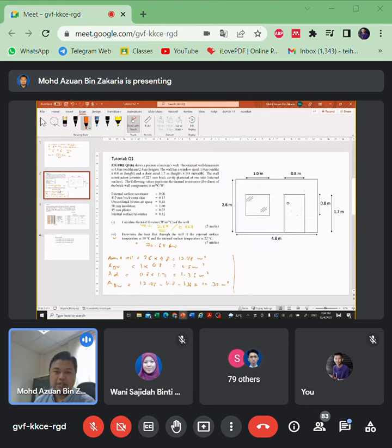Now the next step is just to find the U value. So U value for brick wall. The following values represent the thermal resistance, so it is easy. This is actually the R value, so no need to calculate R value for each material.